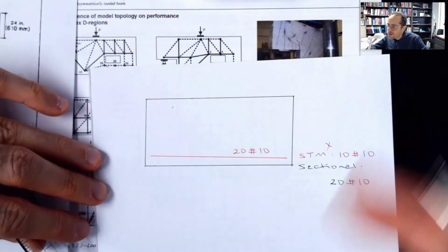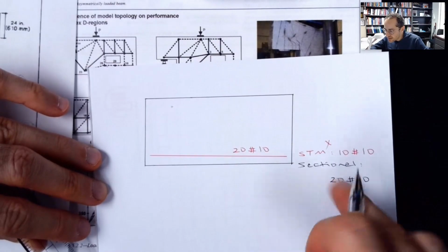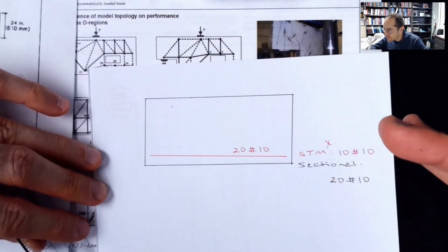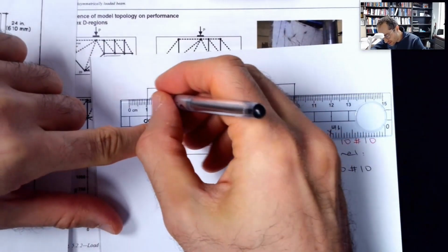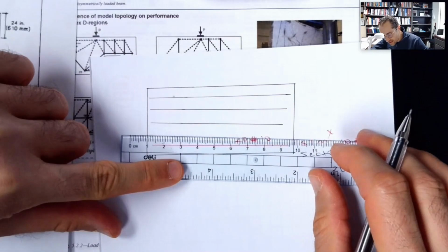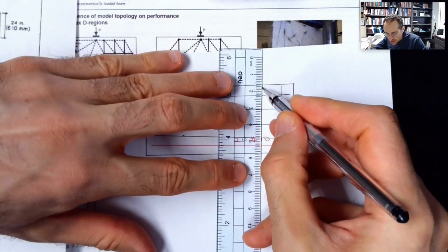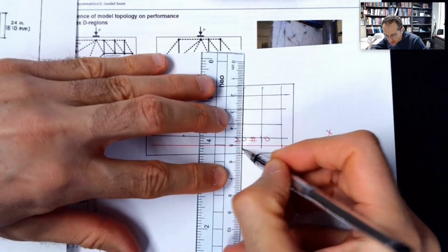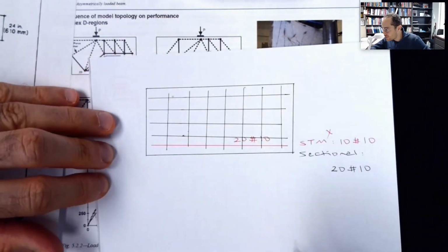So fine, if you don't want to do strut-and-tie, go use sectional, but use the strut-and-tie requirements, not the model development, and still put in your crack control. That's what I want to say, because deep members definitely need that mesh, both ways, both sides. So now, yes, this would be more conservative. It would be a good design. So never neglect crack control, even if you use sectional.